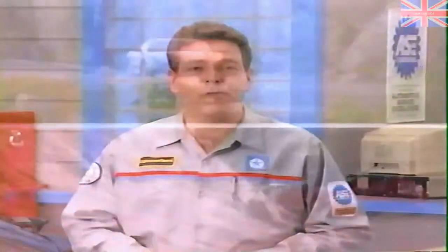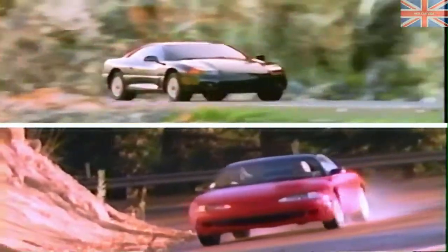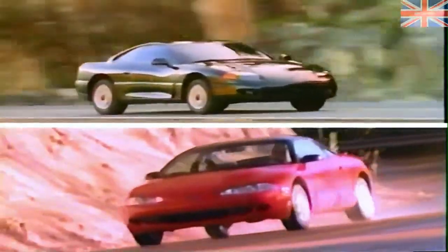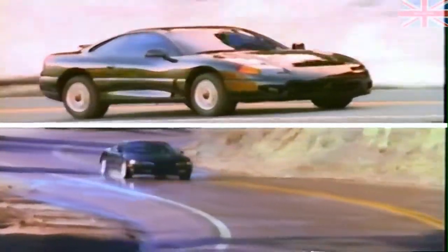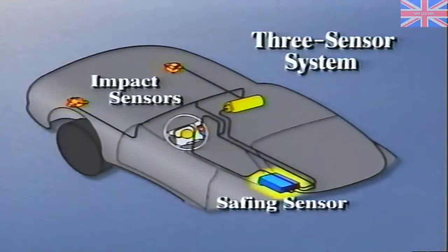There are two types of airbag systems currently used on MMC vehicles. The first type is a 3-sensor impact detection system used in the 1994 Stealth, 1995 Talon, Avenger, and Sebring. It has 2 impact sensors in the front corners of the vehicle and a safing sensor in the SRS Diagnostic unit. All of these vehicles have dual airbags.